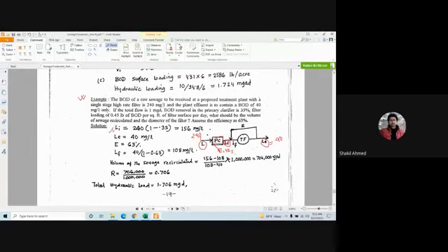Yes, sir. Li will be 240 into 1 minus 0.35, 156. So as you can see, 240 has become 156 here. So reduced. Who has reduced this, guys? Primary clarifier. 240 minus 156, that much has been reduced by primary clarifier. Okay.